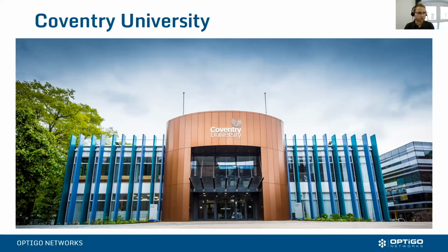BMS-wise, the BMS team consists of myself and two other members of staff, our apprentice engineer and a BMS operative, so a pretty small in-house team, supported by our contracted maintenance firm, SSE. From a BACnet perspective, we have over 400 Siemens controllers throughout the system, and currently just over 1,100 BACnet devices integrated into it. 90% of devices are IP, with the rest being MSTP, and we've got about 95% coverage throughout all the campuses. All of the devices are integrated into our Desigo CC system, consisting of about 10 different servers.